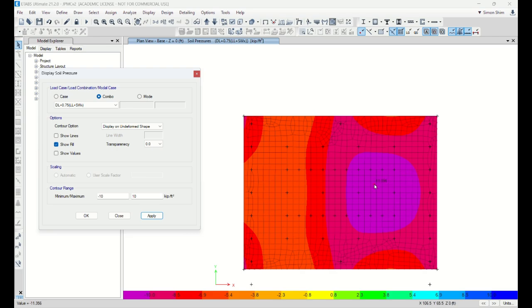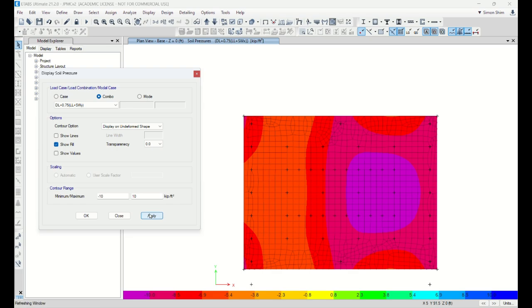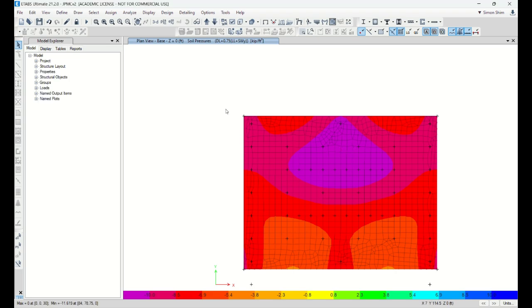So on the right side, you're gonna see some more compression, right? The left side is tension due to the wind load. So combined with the gravity effect, you see that more compression stress is happening here, minus 11. As you can guess, in the Y direction, you see that wind is blowing positive Y, and the compression side is on the leeward side. You see the more soil bearing. So you need to include this part in your report.